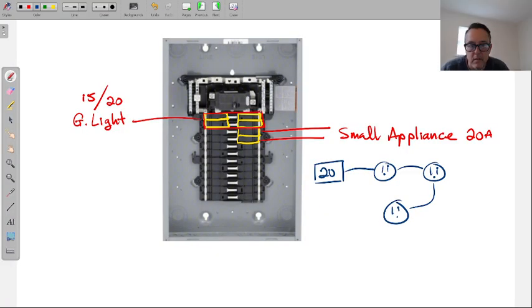Blenders draw good amps, 6 amps, 8 amps even. Same thing air fryers. When they're on, they're on. So individually they're 6, maybe 8 amps, that doesn't seem like a lot, but if your microwave's on and you got the coffee maker going in the morning and you got that panini press kicking, that's going to accumulate maybe more than 20 or pretty close.